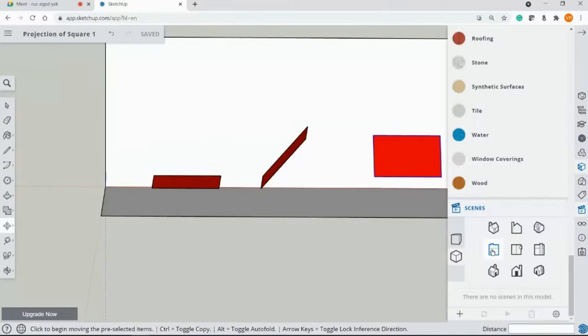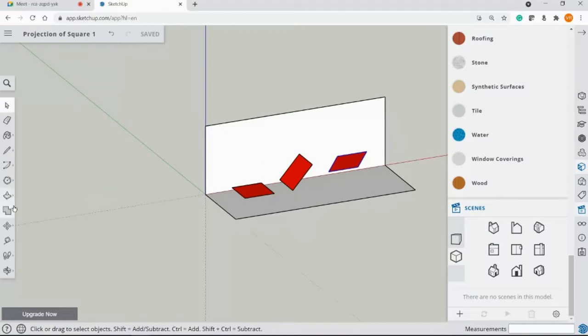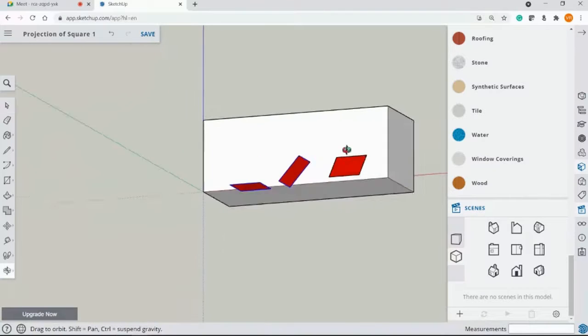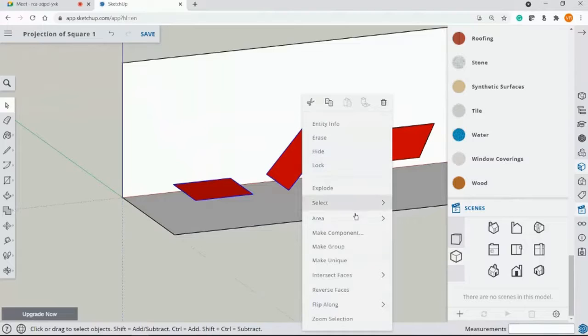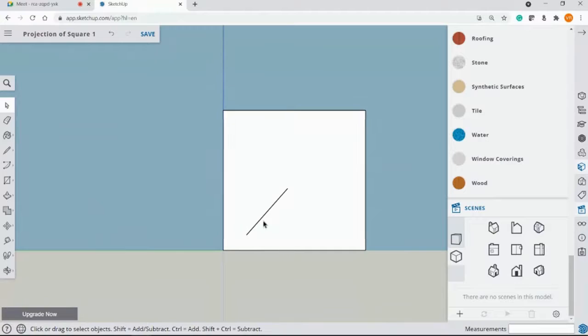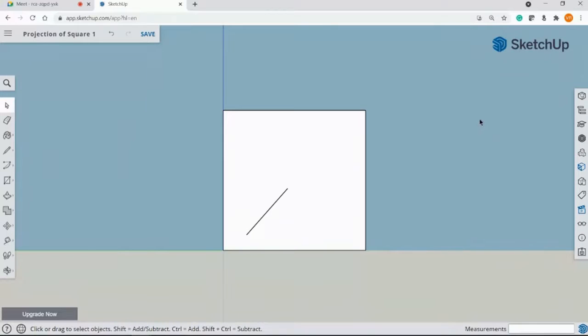You can see here. Let me just draw a plane here so that the side view is clearly visible to you. Let me draw a right profile plane here. Just for a moment, I'll hide these two, and let's see the side view. The angle with respect to the horizontal plane will be here. The angle with respect to the vertical plane will be here. That is what you have to determine, that is what they have asked.